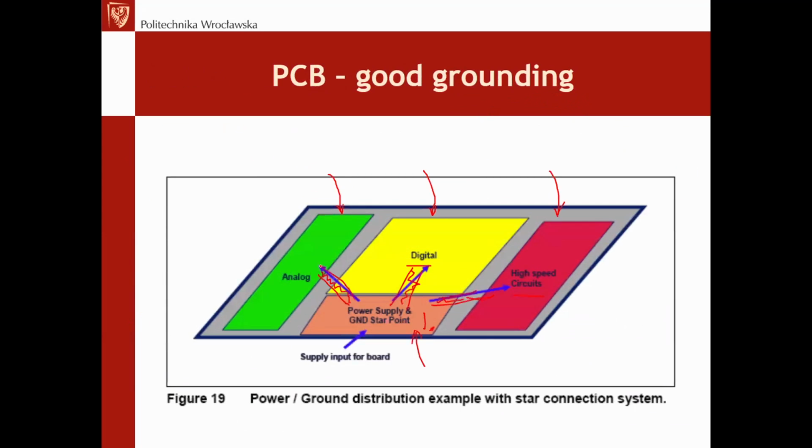Then within the analog area, we can connect using multi-point. That's still fine. It will work well, and it will guarantee good grounding.